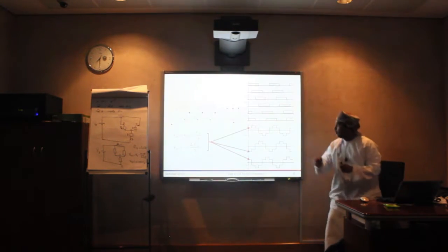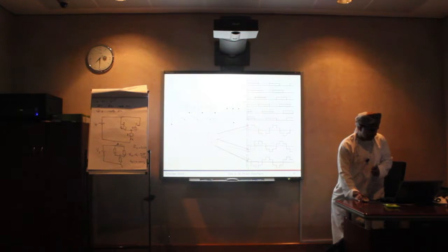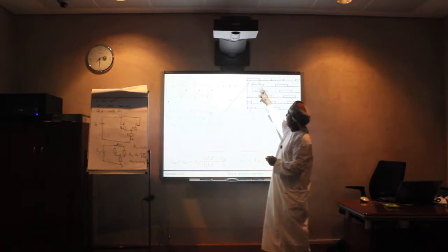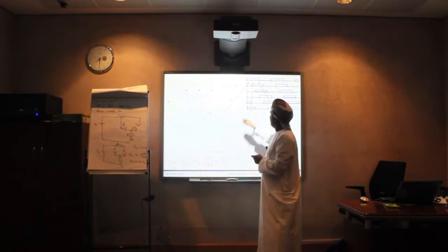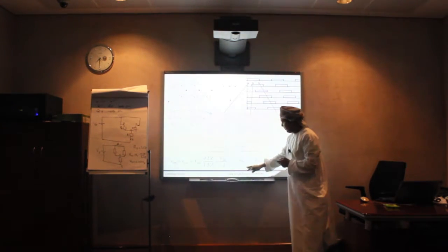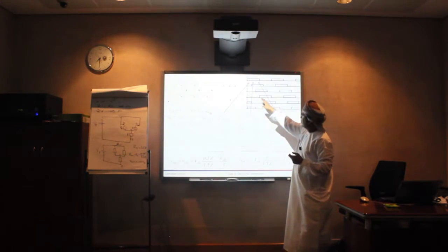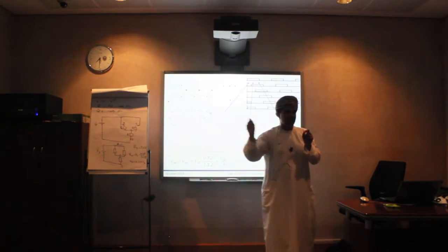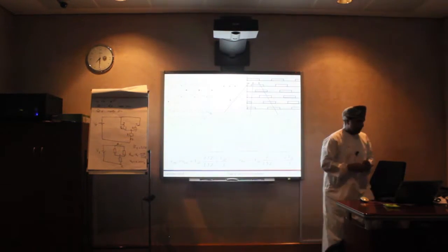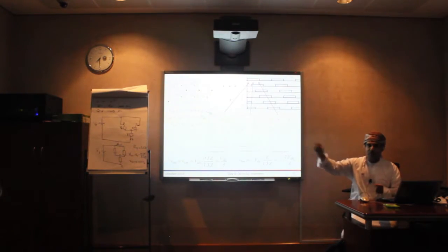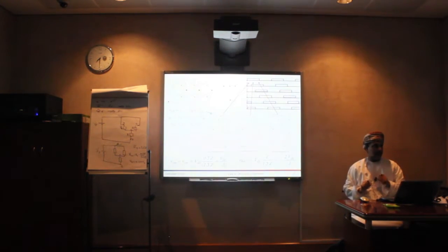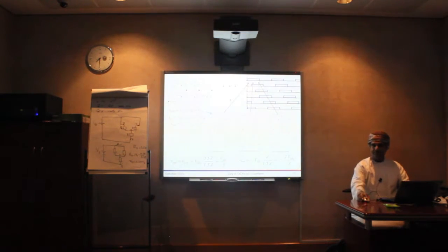And then if I go to the next interval, you can continue with the same circuit like this one. If you apply this, you will get VAN, which is 2/3, and so on. So you will get like 6 pulses in the output like this. You can apply a circuit like those for each interval in order to get the value of that voltage. Did you get it, Shabab?